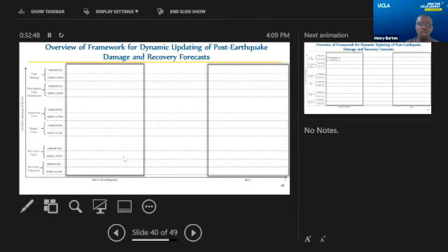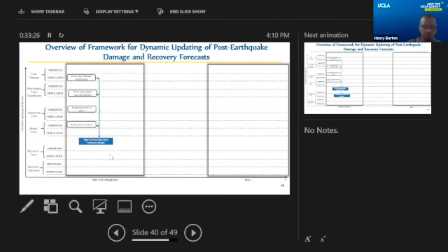If we take two snapshots in time, one at day 0 and one at day t, we can have a priori on the pipe damage distribution, meaning we're just using fragilities that we developed, or fragilities from hazards, or wherever the fragilities come from. And then we have a prior distribution on the repair time, meaning we have maybe data from past events, or maybe even other water distribution systems that we use to approximate the distribution of the repair time, as well as the inspection crew.